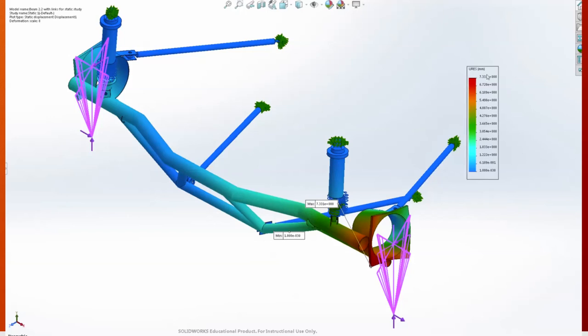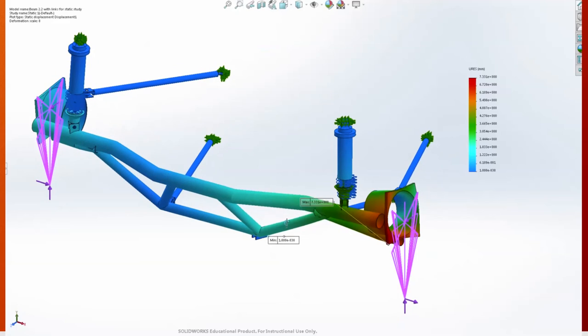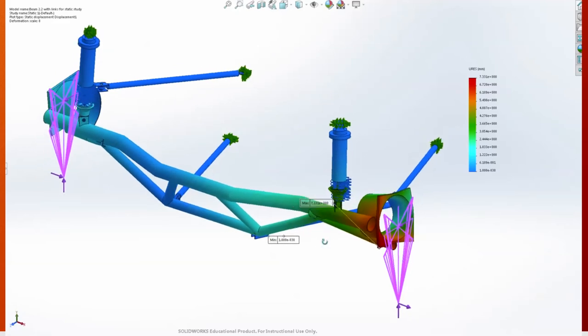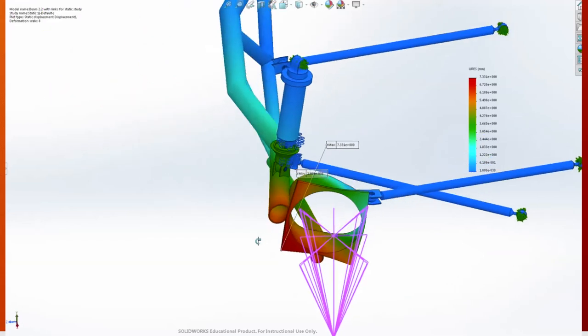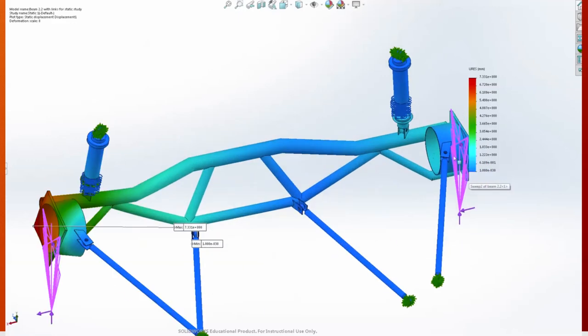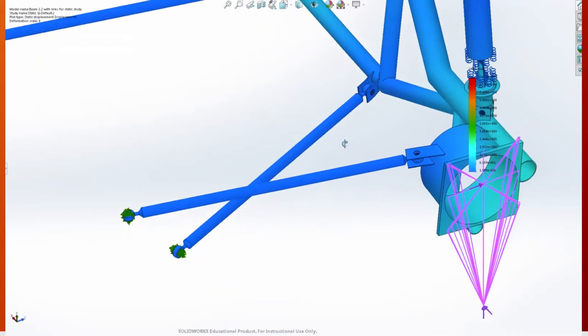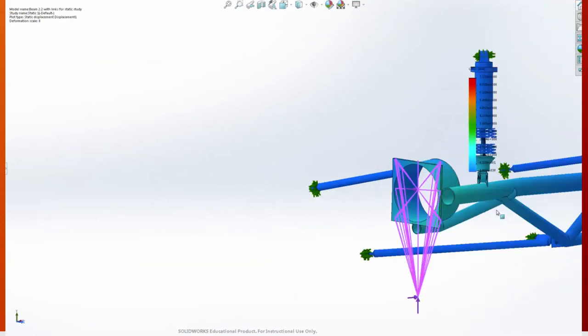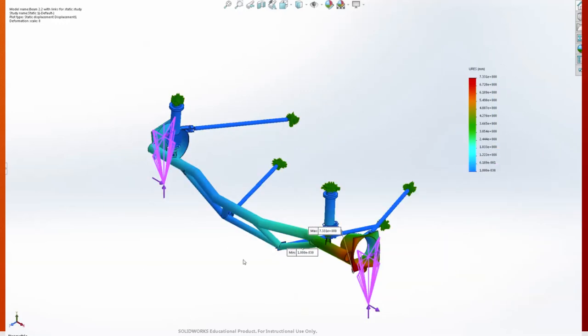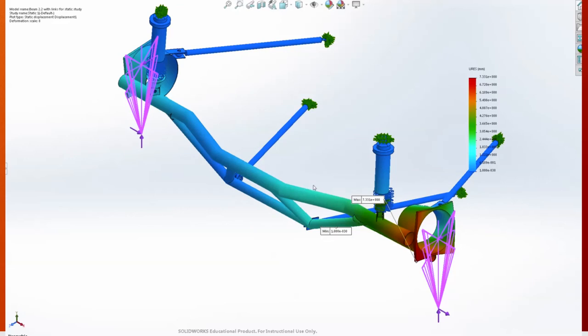So this was the displacement. The scale is 8. So we do deform 7 millimeters, which is not acceptable. That's about a 1/4 inch. So that is not an acceptable amount of displacement. However, this is a first iteration of the truss style beam in order to distribute the loads more evenly throughout the material that is used. So even though this beam could not currently be put on the car for competition, it is a direction that seems more promising than just adding larger tube diameters and bigger wall thicknesses.